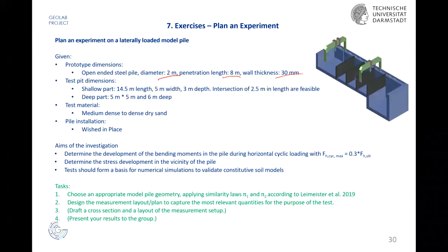That's our aim. We want to apply cyclic loading with a load factor of about 30% of the ultimate load. Second, we want to determine the stress development in the vicinity of the pile, so what is happening around the pile. And the test should form a basis for numerical simulations to validate constitutive soil models. This is our idea. This is why we perform this test.